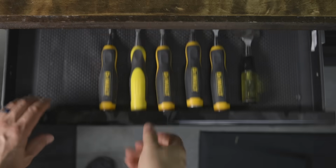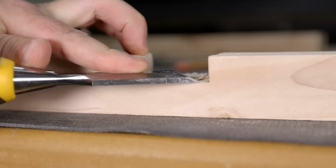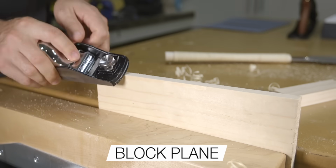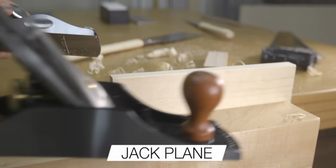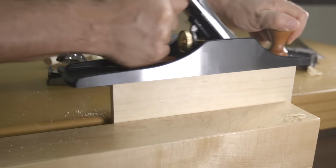Alright, let's finish this video off by talking about a few terms and tools used for shaping wood. First up is the wood chisel. There are many different sizes and shapes available, and they're all great tools for shaping wood. Next is the hand plane. Hand planes, again, is a general term. So for example, I have a block plane here that is used to shape edges of stock and to remove material where needed. The other plane I have is a jack plane, and as you can see, it's much larger than the previous one, and this one's great for general purpose planing and for shaping and flattening.